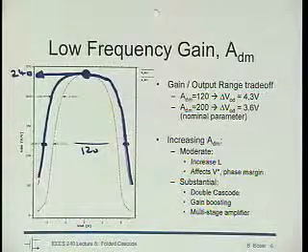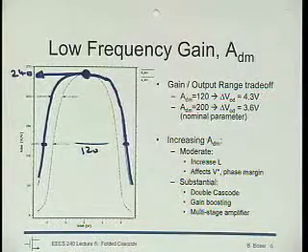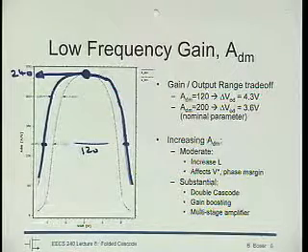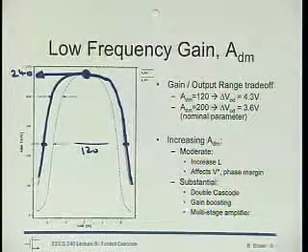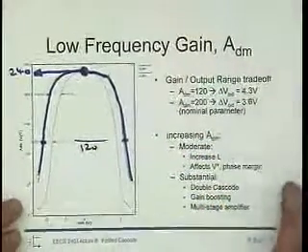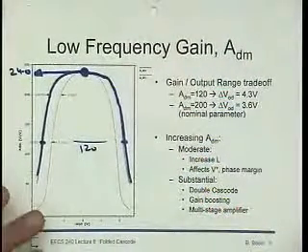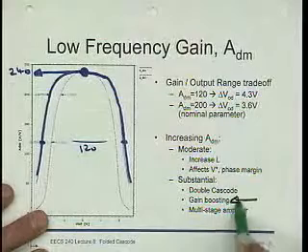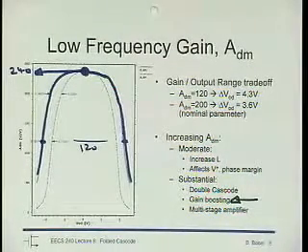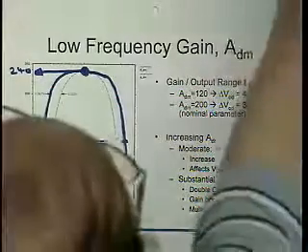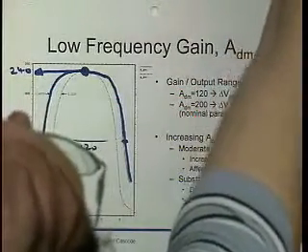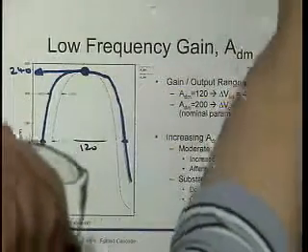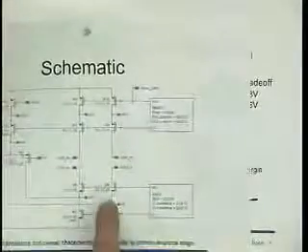Remember that amplifier that we wrap around the cascode? That would certainly help, and that wouldn't require that we introduce bigger devices. Does gain boosting affect our phase margin or not? Well, here is the cascode.